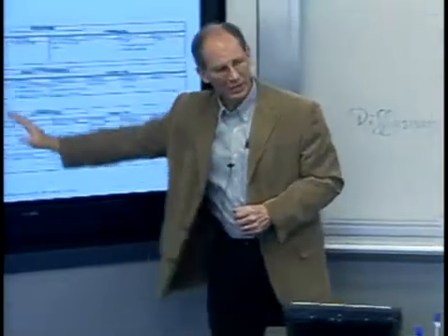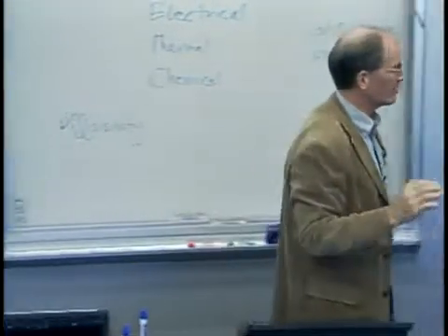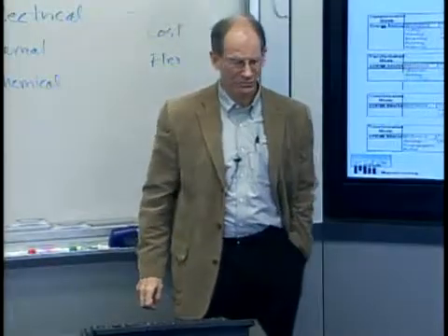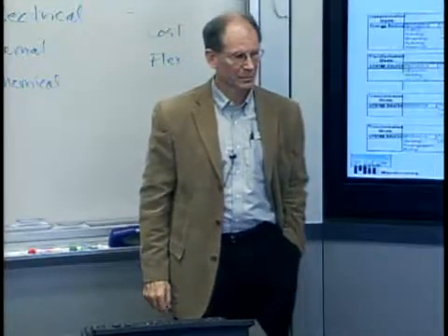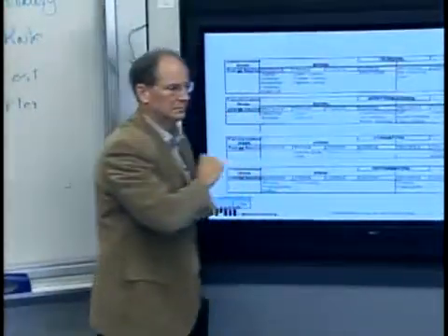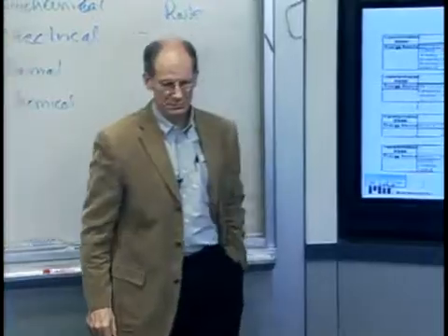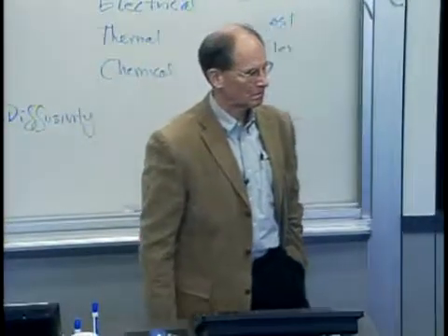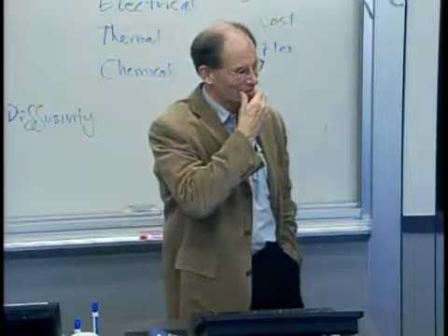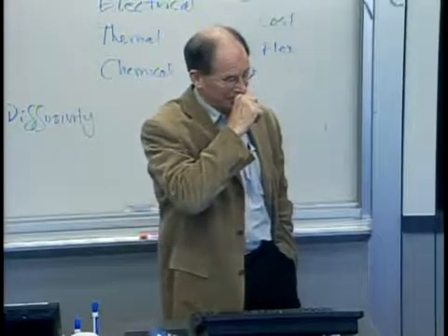But if I look at this broadly, what do you think is the most flexible? If I look at the taxonomy, what area would you look at for high flexibility? Serial processes, and why? Because you're working on a local area at a time, so it gives you more flexibility in terms of feature by feature, and then also part by part.